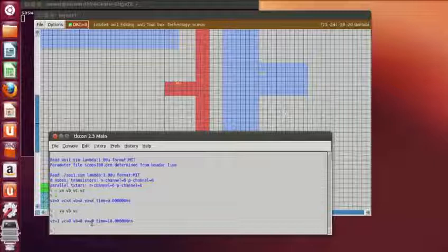So when A is 0, B is 0, this is A dot B, output is 0. Then we have OR. This is the AND output, then this is the OR input. So the total final output will be 0 again. So this is AND OR invert. Whatever the output from here, we'll get an invert of that. That is, we got 1.